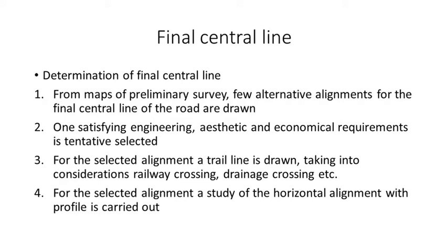Okay, next, in the preliminary survey we are going to use a traverse survey. Okay, and there is one running traverse along the proposed center line of the road. This traverse should consist of a series of straight lines with their distances and intermediate angles measured very carefully. The traverse should be done using a theodolite. As you know, the theodolite is the equipment used for angular measurement. Okay, a transit theodolite you can use for this traverse, and angles are measured with the double reversal method. So this method you can use for the measurement of angles in the case of a road traverse, or traverse survey.